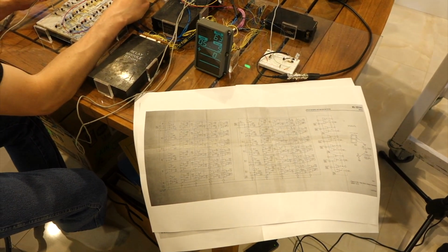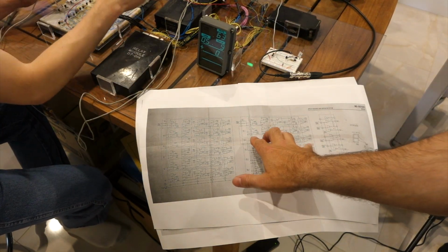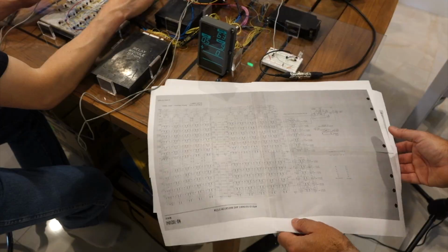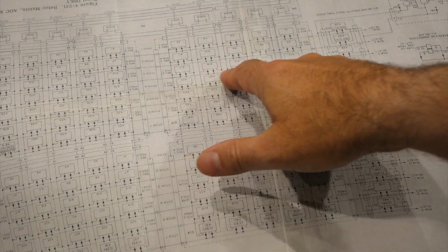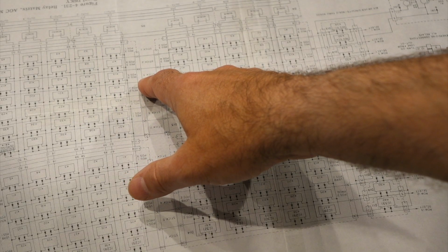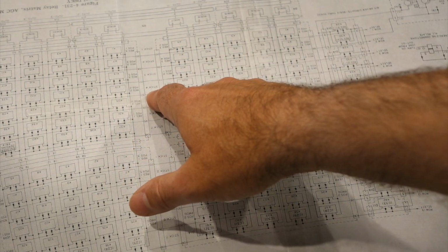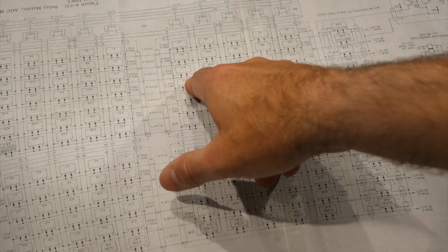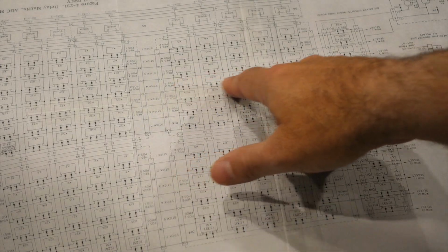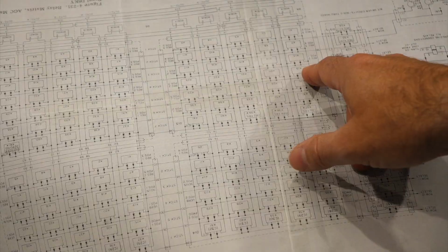So the way this works is every digit is connected to a bunch of relays, banks of 5 relays. And these are the relay coils. You have one line that selects the digit, selects one end of the coil. That's this line over here. That goes to negative, and I think that's the one that's not working. And then for each relay you have 2 that you bring to the plus: one to latch it, and one to unlatch it. But the fact that the whole digit doesn't respond means that it's probably one of the lines common to the 5 relays.